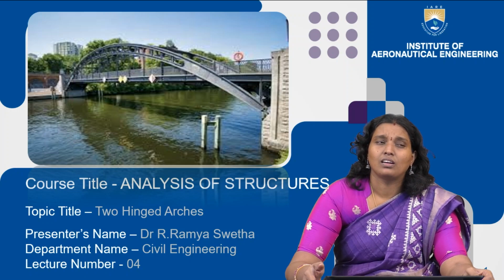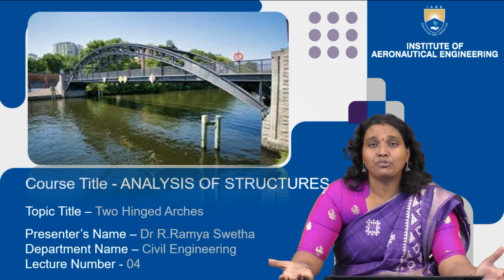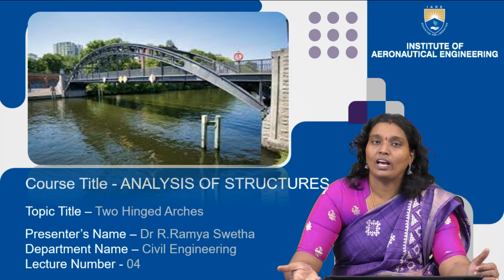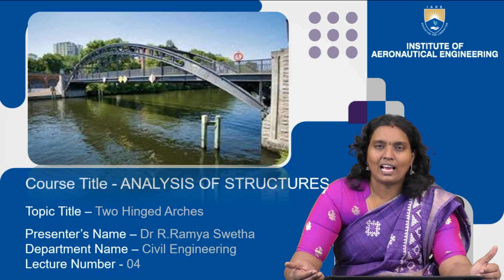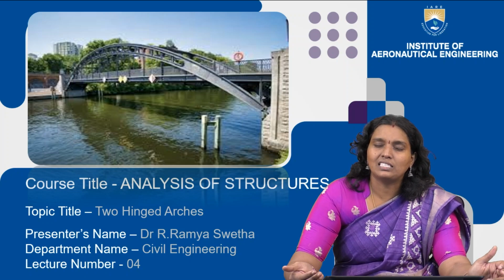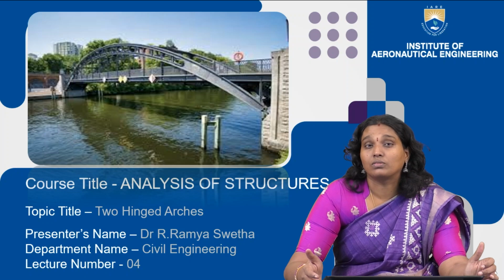In this type of arches, we have to understand how load conditions are distributed based on the number of hinges. We have different types of arches available according to their geometry, the material available, and the hinges. According to the hinges, we classify them as two hinged arches as well as three hinged arches. Whenever the arch has two hinges at its supports, such arches are known as two hinged arches. And when there is one more hinge at the crown, such arches are known as three hinged arches.